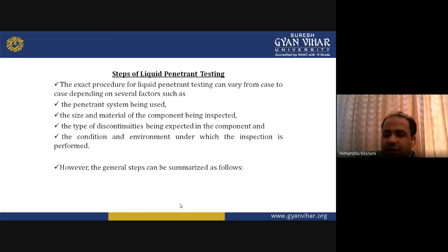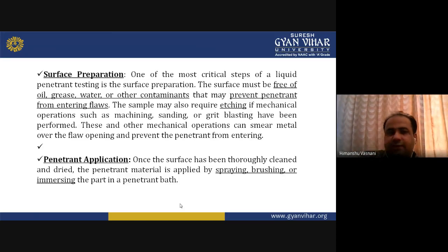So now we are going to summarize the general steps. The first is surface preparation. It is one of the most critical steps of liquid penetrant testing. The surface must be free of grease, oil, water, or other contaminants that may prevent penetrant from entering flaws.